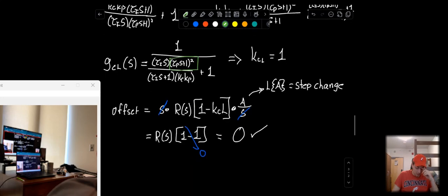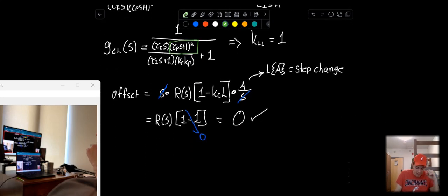Because again, our magnitude here was arbitrary, it was just A, right? So I guess technically we should have A here as well. I missed that piece. Obviously, if A was 1, then it wouldn't have mattered. But for any step change of any magnitude, we have shown that for any order of process transfer function, specifically in this case, we used a second order, that offset will be 0.